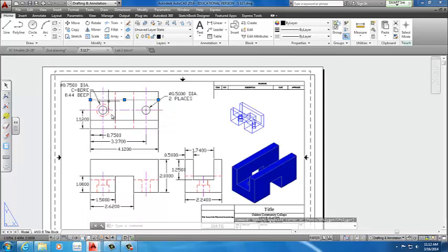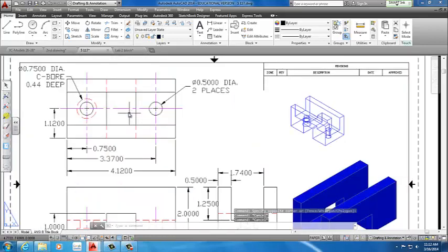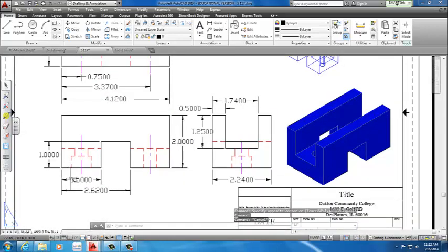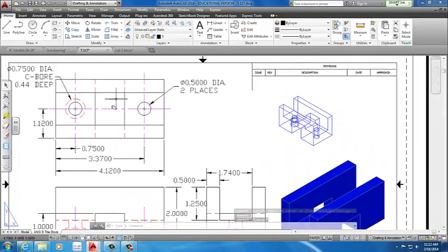What we need to do next is create this one and this one from the quadrants of this top circle. In addition to that, we need to create these 2 lines going directly down, which is the cut open. To do that, you want to make sure your O snap is on and quadrant's on. 1.5 on this side and 1.5 on this side. Right now that gives us mine's cut open. Not sure you guys can see it.